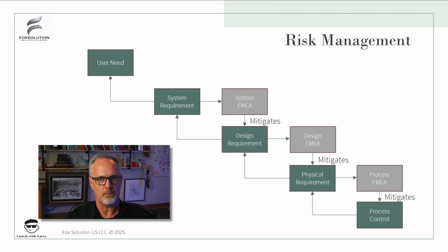And then finally, the process failure analysis takes those physical requirements, like the 3/8 inch bag seal, and defines all the ways that that bag seal wouldn't be delivered. So you get a hair in the seal, which creates a tunnel, or we have delamination of the bag. Those different problems are associated with the manufacturing process: cleanliness of the process, or how the sealing's done, the pressure of the seal, temperature of the seal. And then what ends up happening is we have a set of process controls that are necessary to assure that we get that 3/8 inch bag seal.